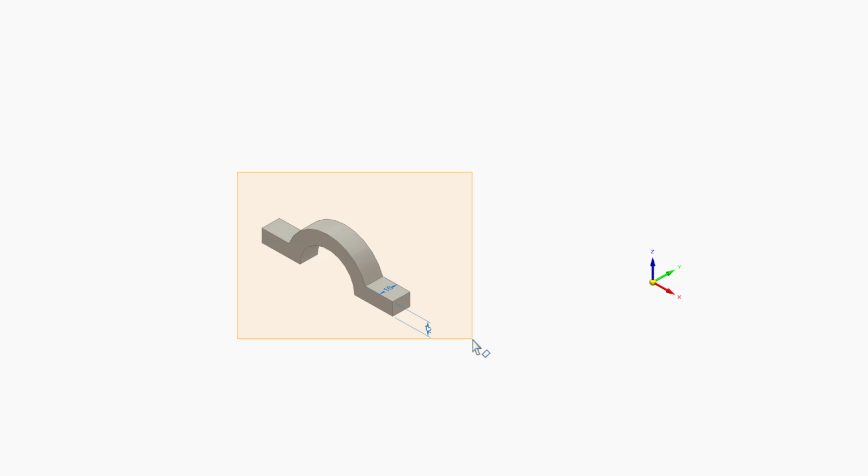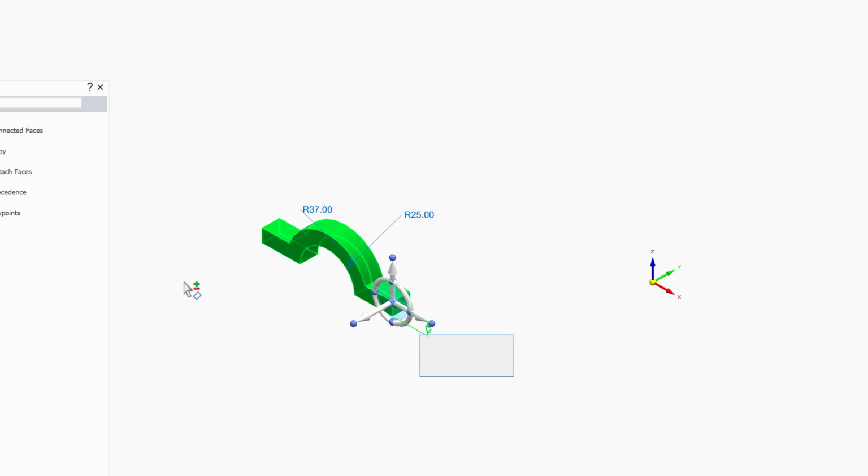To reveal the wheel. And you have to be in the synchronous mode. So I'm going to click on it and highlight it. Now I'm going to move the wheel, go to the center, and align it exactly with the center here. Where is the center? I should see the concentric.